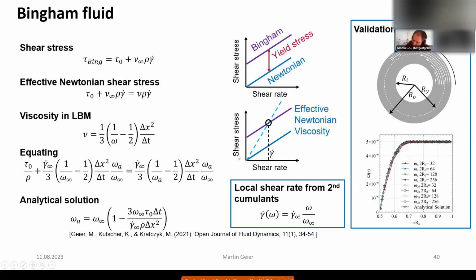Now, what you have to do is, in this model, you have to be able to set an infinite viscosity, which, of course, in the Navier-Stokes equation is always difficult to do. In Lattice Boltzmann, you have to set a zero collision frequency, which is much easier to do because I just said it's a zero, not to infinity. Yeah, so this is much easier.